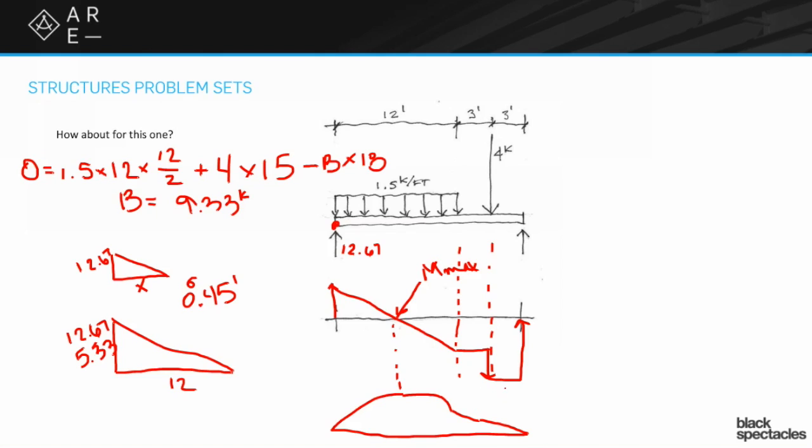And once again, just find the system that you feel comfortable with for how to think about these things. But if you think of it as the value of the shear diagram telling you what's going on in the moment diagram, as that sloping line goes, the value is dropping at every point, and you can see that the curve, that slope is changing and becoming closer and closer to zero until it gets to that maximum point. So same kind of thing. Whatever system you find that helps you see these things or think of them graphically, that's what you're looking for.